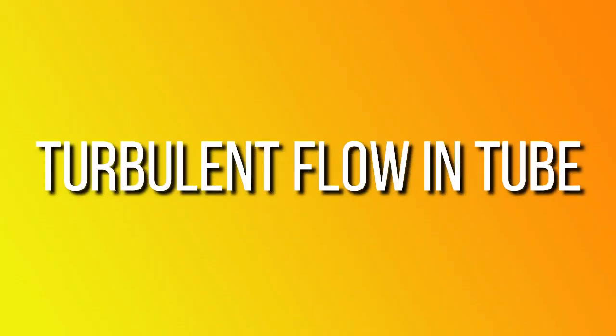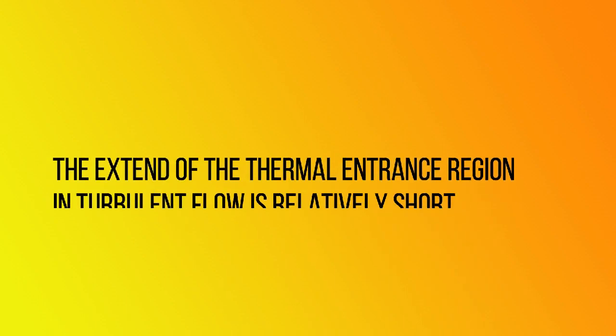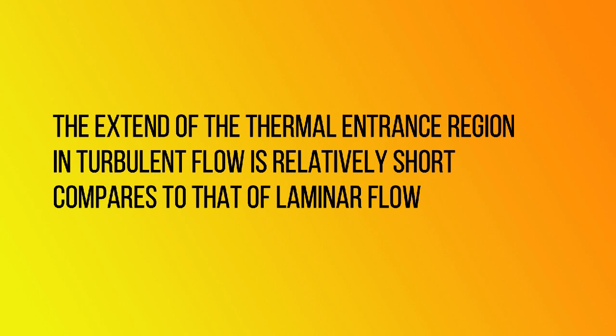Moving on to turbulent flow in tubes, there is an additional mechanism, commonly termed eddy transport. It is intense, providing much better transfer of energy across the flow at a given axial position than in laminar flow. Another thing in turbulent flow is that the extent of the thermal entrance region is relatively short, whereas in laminar flow it tends to be longer.